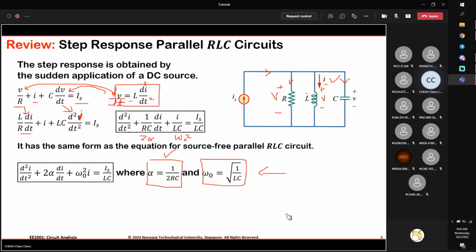If you look at these circuits, at steady state, this will become short circuits, all right? This will become open circuits, no more there. And because this is short, this voltage will become 0. If the voltage across the resistor is 0, remember no current can flow through it, right? IR will be equal to 0. If you're not sure, just use Ohm's law to verify. V over R is I. V is 0, divide by any R, you get 0 volts. Correct? You get 0 amperes.